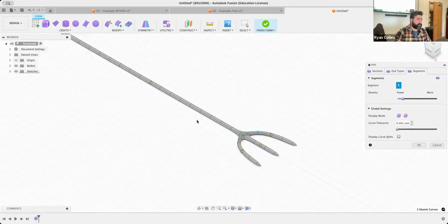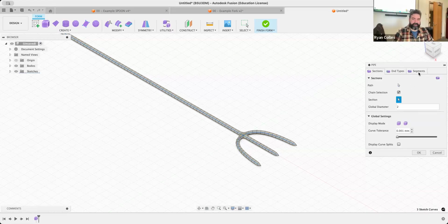So obviously there's a few more steps involved in this, but you don't have to do everything first. Meaning if you had just started with just that rod, we can also expand off of that. You can leave the ends open. You can add complexity if you want. The more complexity it has, the smoother it'll be, but there's more points to try to control. But play around with these tools. There are a lot more options within the form workspace, but that'll get you there.